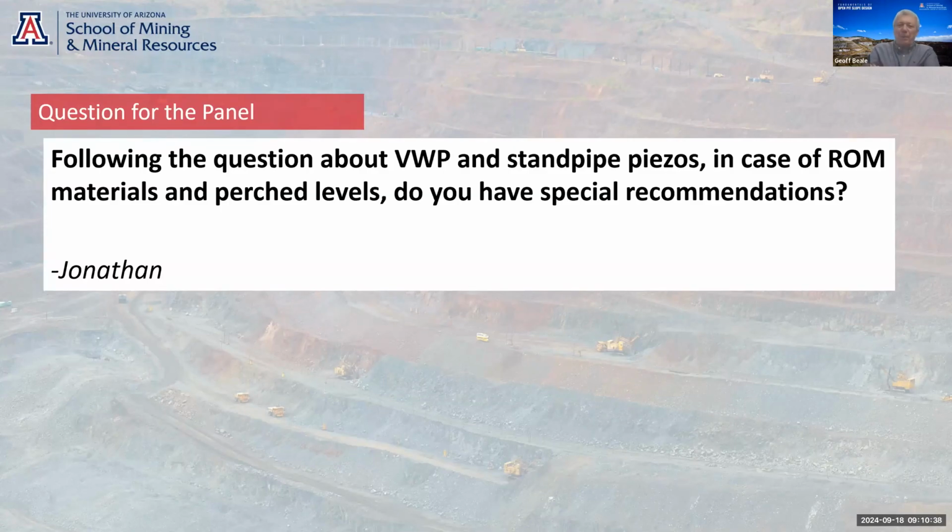So the problem with raw materials is getting the grout to stay in the hole. So I think we'll answer that question in about 2 months' time once we've done some experiments here. But I think if you can get the grout to stay in, that's the best way to do it. If you can possibly put in some casing to minimize grout loss. Other option would be multi-level standpipe piezometers.